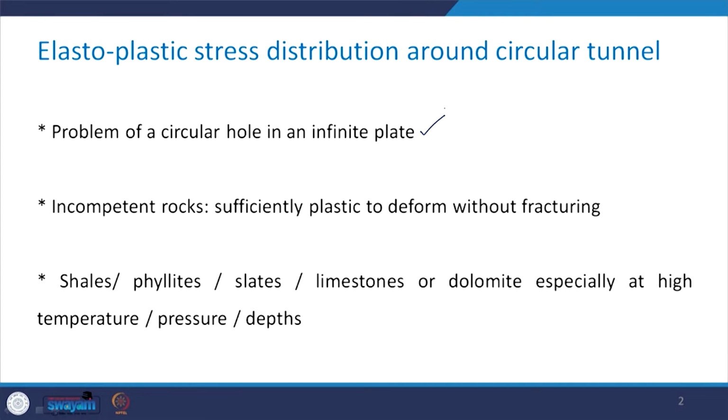In the case of incompetent rocks which are sufficiently plastic to deform without fracturing, such an elasto-plastic situation will be relevant. Rocks such as shales, phyllites, slates, limestones or dolomite exhibit elasto-plastic behavior, especially at high temperature, pressure and depths.